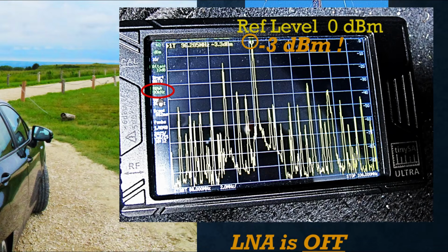Also, I set it at 30 kilohertz for the reason I just discussed. So now you can see that we can get some pretty weak stations, but not down to minus 110 or minus 120. This is minus 90 here. The bottom is minus 100. So that's really due to the limited dynamic range of this receiver. Spectrum analyzers are receivers, right? So a spectrum analyzer has the same kind of issues that we've been trying to address in our receiver designs. But we can see some spaces between the channels that we couldn't before because we got the resolution bandwidth set to 30 kilohertz. Yay!